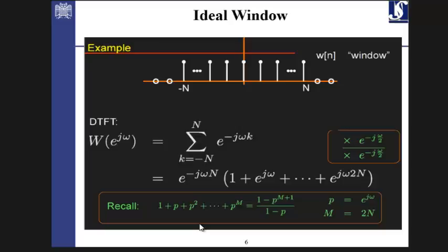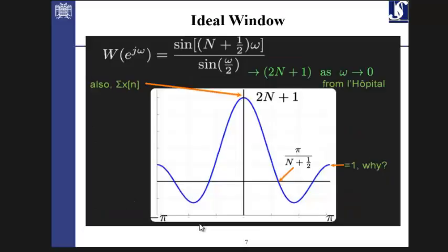And the corruption comes from this point that windowing in the time domain corresponds to the sinc in the frequency domain. And we know that in the frequency domain, the DTFT is periodic. So this sinc function will be periodically repeating. And we know that this sinc function in the edges, in the final ends, in the limits, is not actually zero, such that periodicity of this block, of this sample or the pattern, makes problems.